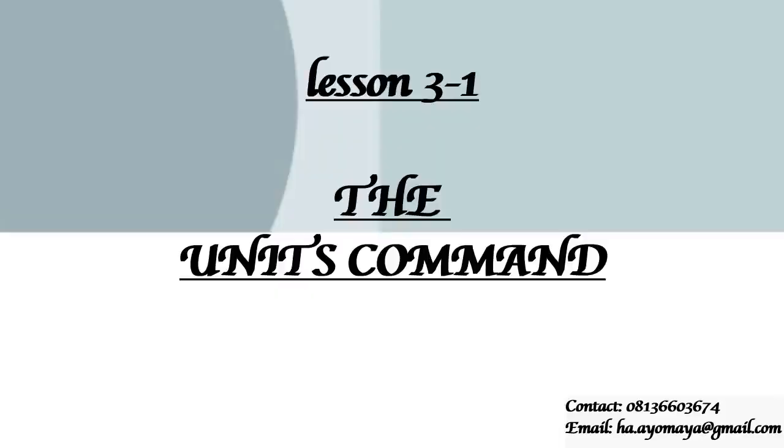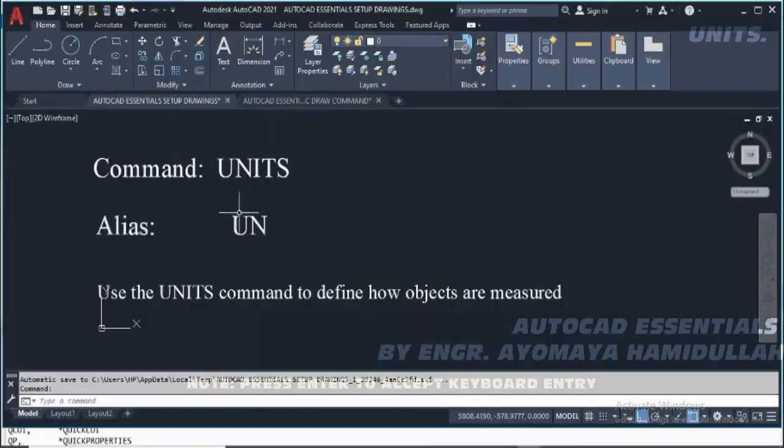The unit command. Choosing unit types. One of the first tasks in setting up a drawing is to choose the unit type. Units define how objects are measured. You can save the unit type in a template. The coordinates that you use in AutoCAD are measured in units that can represent any real-world measurement, such as inches or millimeters.